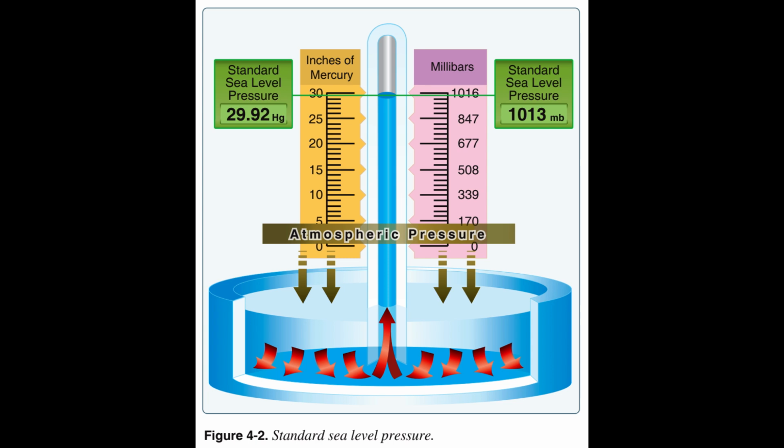Using the National Oceanic and Atmospheric Administration (NOAA) website, www.srh.noaa.gov/epz/wxcalc/densityAltitude, enter the 22.22 for 8,000 feet in the station pressure window. Enter a temperature of 80 degrees and a dew point of 75 degrees. The result is a density altitude of 11,564 feet. With no humidity, the density altitude would be almost 500 feet lower.